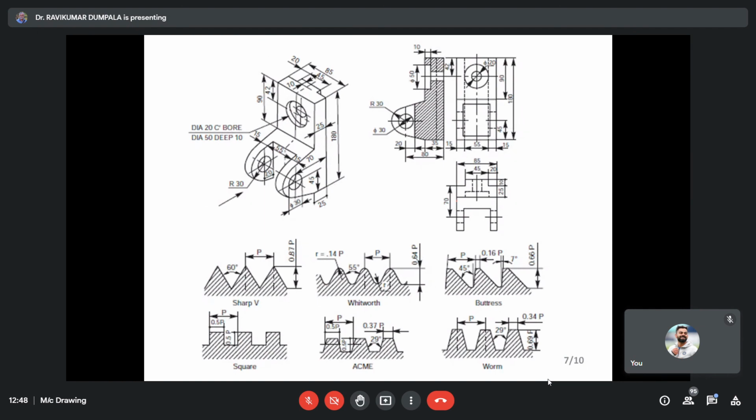This is orthographic projection, nothing but a sectional drawing. Mostly we do sectional drawing. In engineering drawing, we have drawn simple drawings. Here, you will be doing sectional drawing. You see, there is a front view, top view, and right hand side view. They draw the section to show some features. In machine drawing, mostly you have to represent the radius and diameter very clearly, symbolically, which we don't do in orthographic projections in engineering drawing. Here, you have to be very specific about those things.